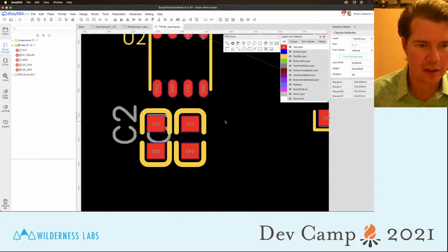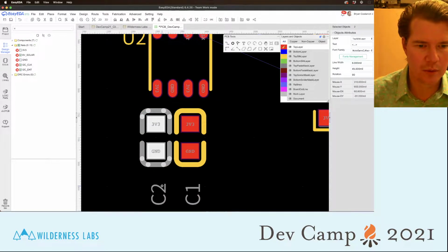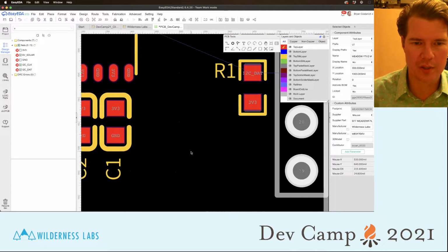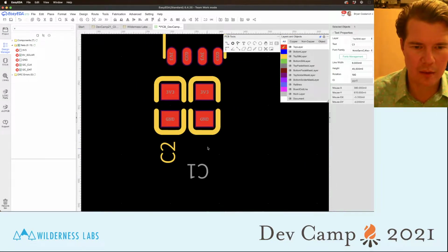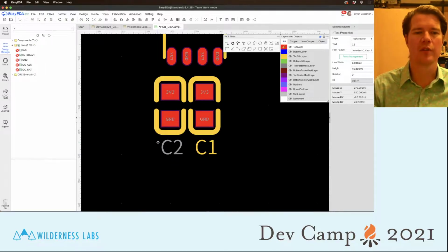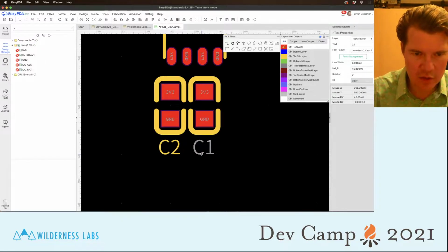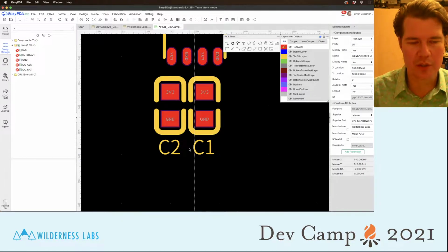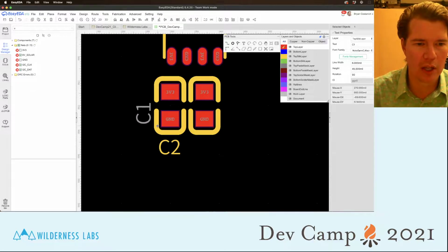And we're going to line this one right next to it. And then again, let's change these to a smaller font and rotate them and place them in a reasonable place. Now, one thing to note about these prefixes is that you generally want to align them all in one or two directions, which means that they should all be facing this way or this way.